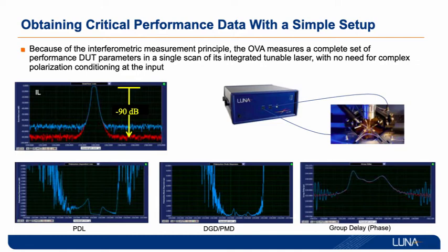They were seeing bandwidths between 15 and 25 gig, chip-to-chip variation for the same exact design. What it came down to was a variable process issue that only showed up in the phase measurements. It was really a group delay phase ripple issue that was causing these strange bandwidth results. You would never be able to unearth that without this completeness of test. This is why we stress completeness of test.